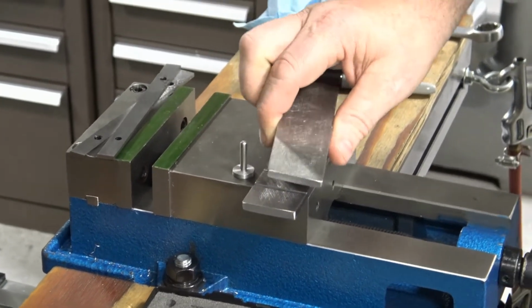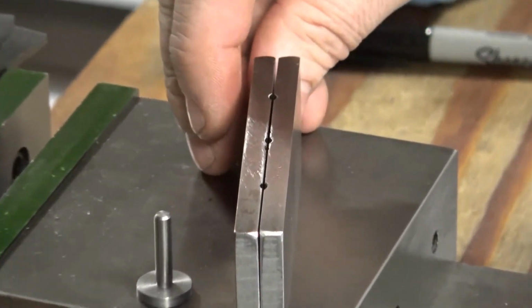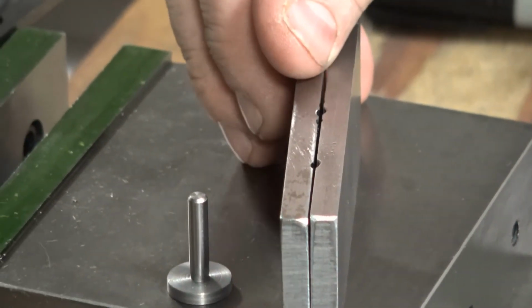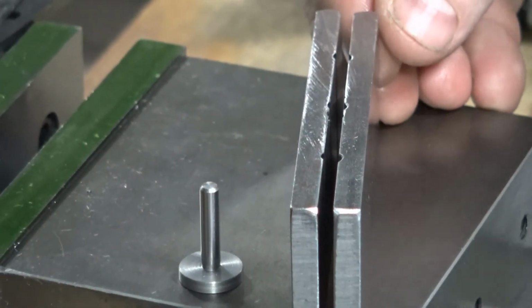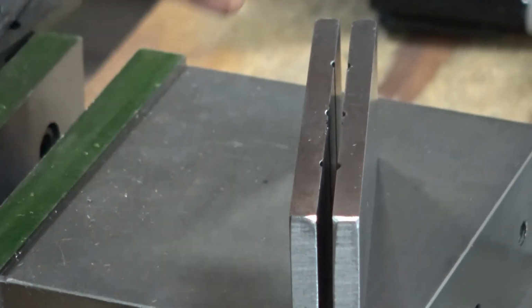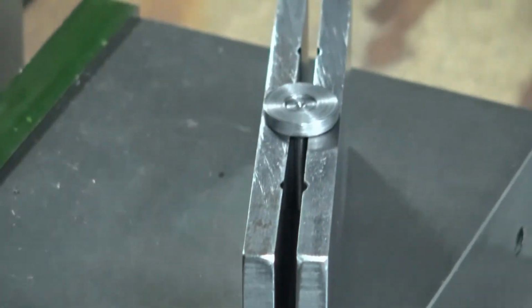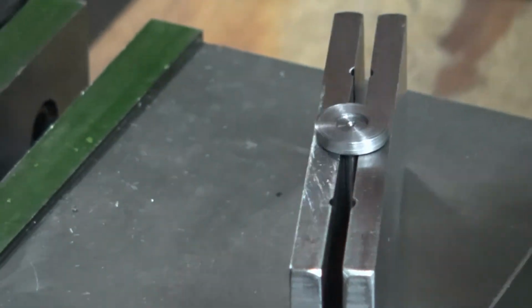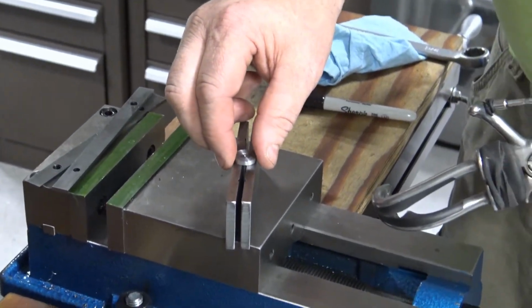So if I put one plate opposing the other and I line up those circles or those radiuses that we have cut into it, right? There's our 3/16 diameter, and I put my workpiece down in one of those grooves and I clamp on it. That gives me good support, and it doesn't concentrate the pressure in any one place that's going to force it to have flats put on it.